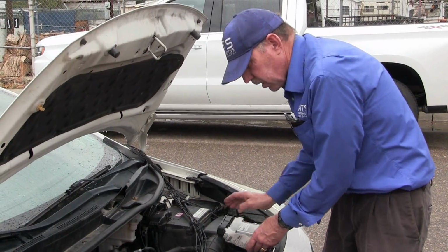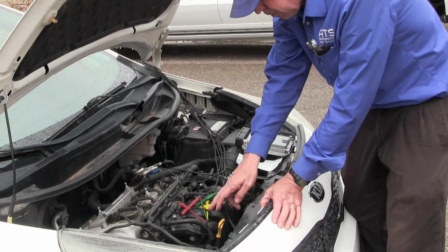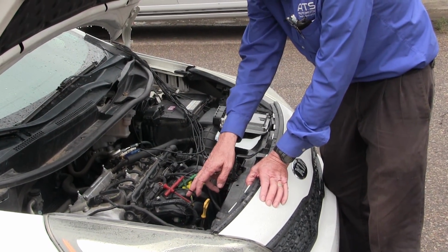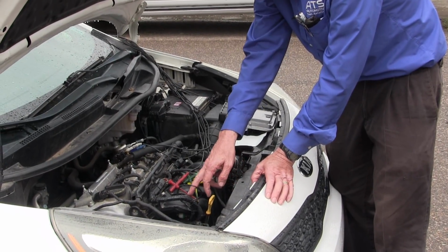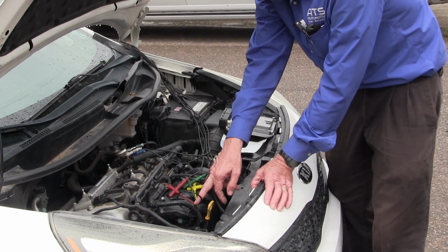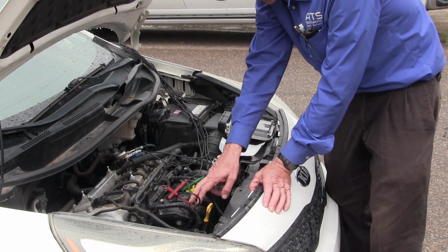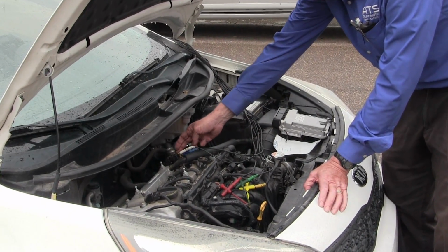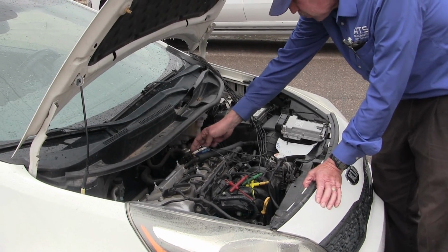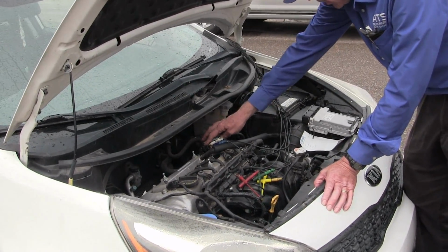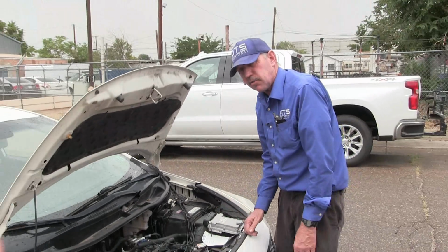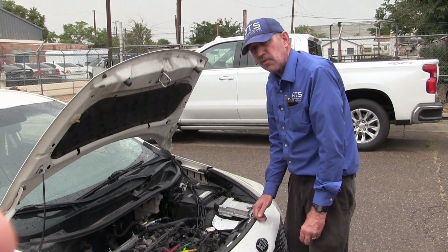But now that we've fixed the wiring harness and I've got the scope connected, channel 1 is the signal for the high pressure sensor, green is the ground to the high pressure sensor, and red is the 5-volt signal for the high pressure sensor. And then I added channels white and blue, which is on the fuel pump, the high pressure regulator control system. So those are the signals I want to look at now. So let's go ahead and take this for a test drive and see what's going on with this vehicle.